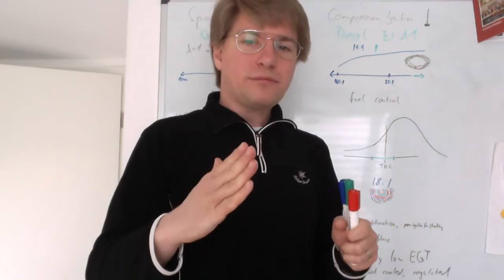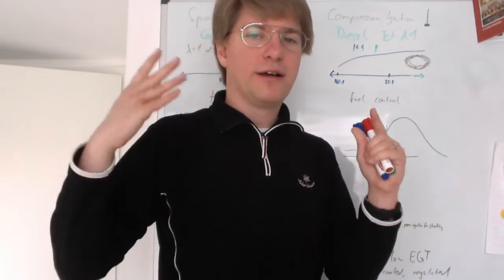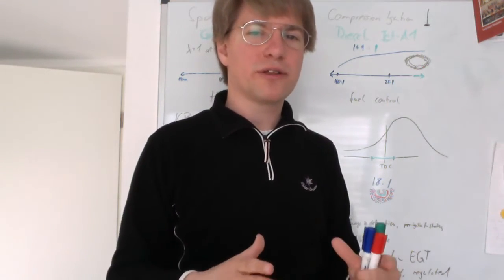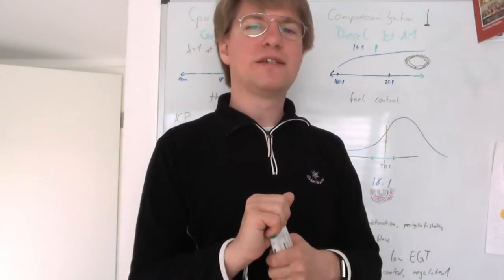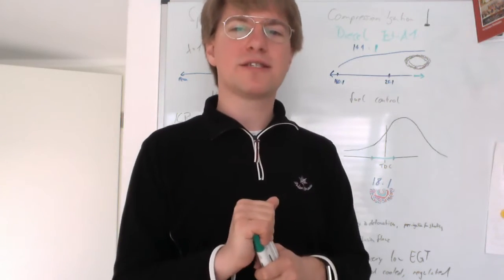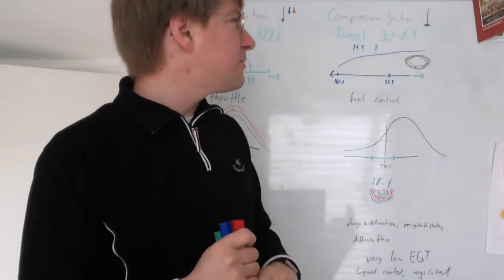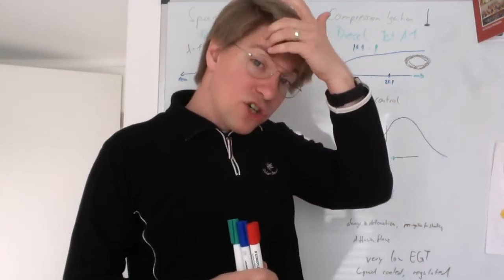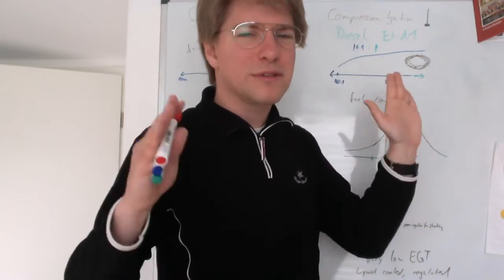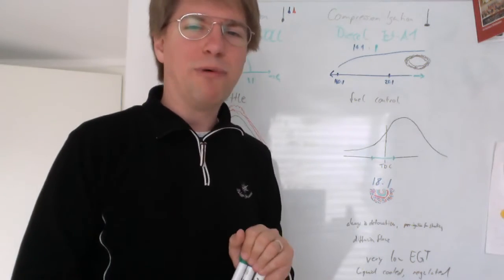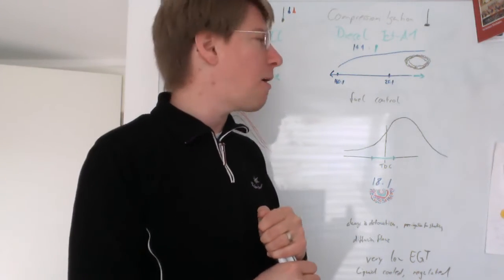Because the compression ignition engine is built to run in detonation. The cylinders are stronger, the pistons are stronger, the cylinder head is much stronger. The engine is built for the additional stress of running in constant detonation, and that's why it sounds so horrible. So the optimal fuel-air ratio for the diesel engine for burning diesel fuel is also around the same. It's at 14.4 to 1 by weight, so not much different from gasoline optimal mixture.